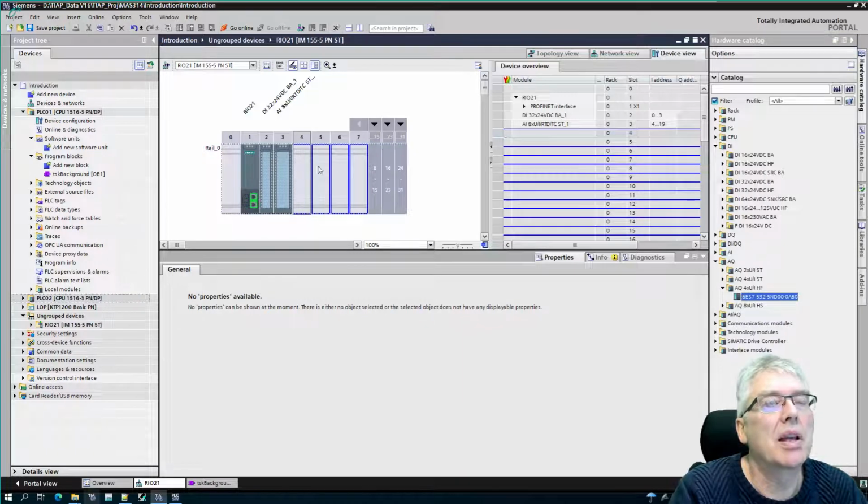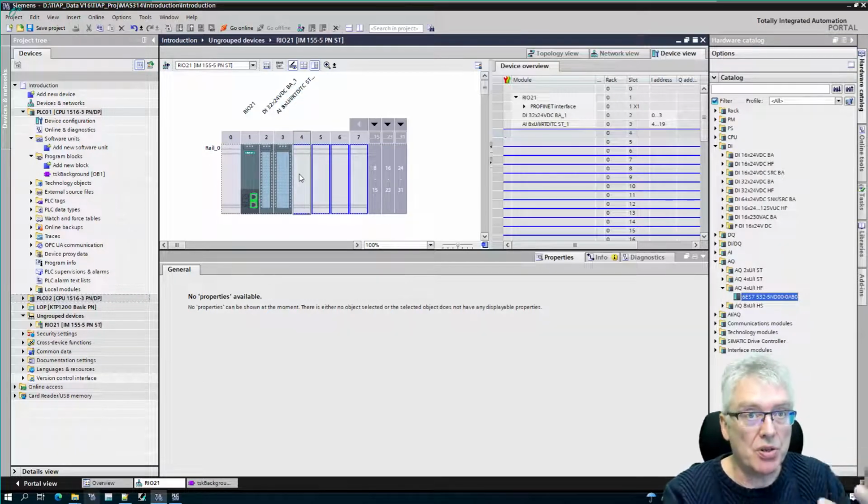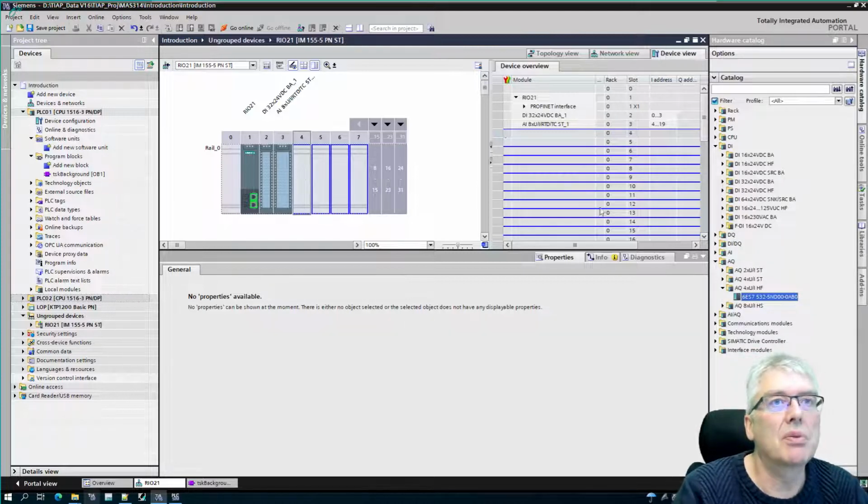So where can I place this one? They have to be contiguous over here because of this small U element connecting these modules. They are actually the bus, the communication bus that goes through each module here. So I have to insert it here and have no spaces.